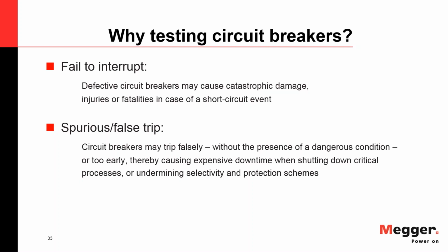Think about a chemical plant. Some of these processes need days to be restarted, or some of the stuff that is made in a refinery has to be in motion constantly. Once it's at rest, you will never be able to liquefy it again. So if you clear every single short duration fault, you can be in trouble because it can cost millions.